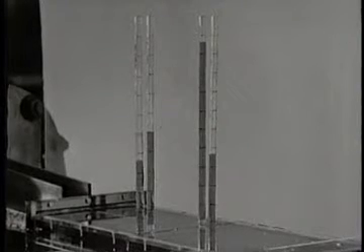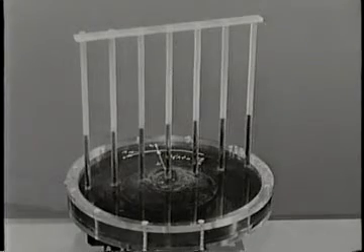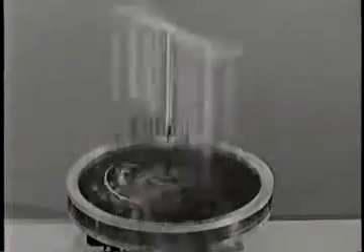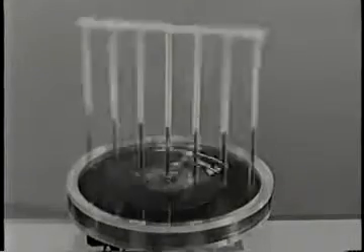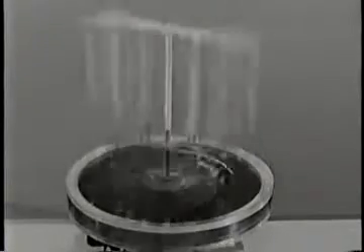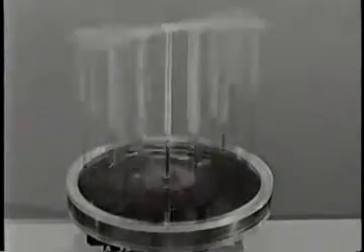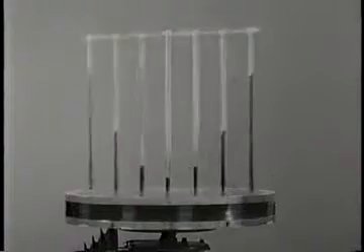These vertical tubes will show the pressure distribution in the tank of water when we rotate it on the turntable. After viscosity brings the water into a solid body rotation, the velocity will increase linearly with radius. If you used Bernoulli's integral, which would be improper because you would be crossing streamlines, you would expect the pressure to decrease with radius. Actually, you see, the pressure increases with radius. This means that the stagnation pressure also increases with radius, and each circular streamline must have a different Bernoulli constant.